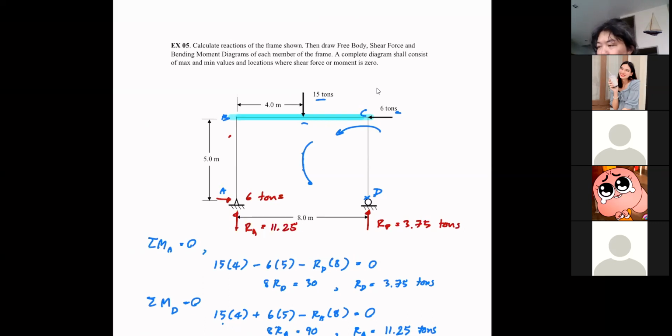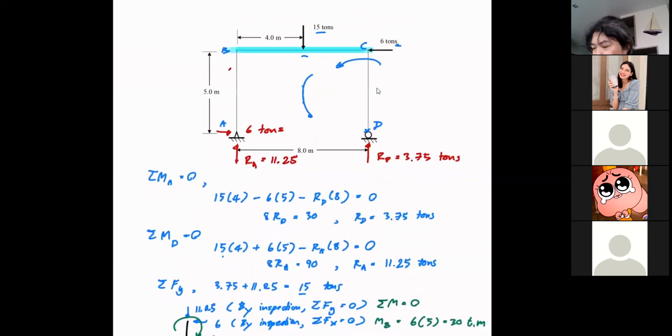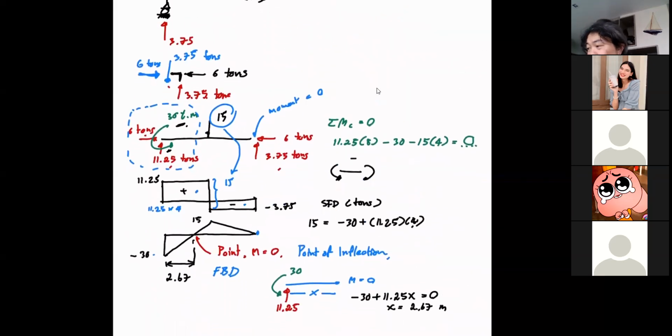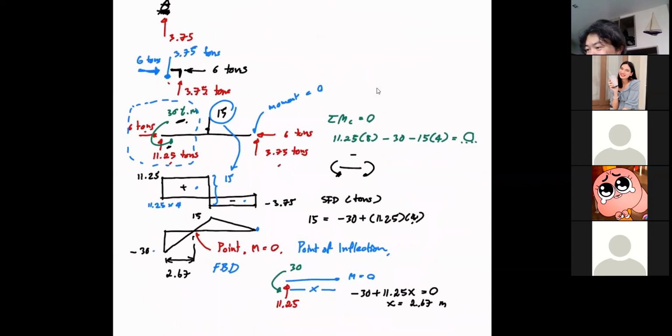And it is going to be most preferable if you can make a connection where the moment is closer to 0. Because if you look at the moment diagram, if you are going to connect this member at this location, it means that your connection must be able to withstand that much moment. So it's a waste of materials. It takes more out of the structure because you want to connect the structure where the force is largest. So that's by any means not the smartest idea.